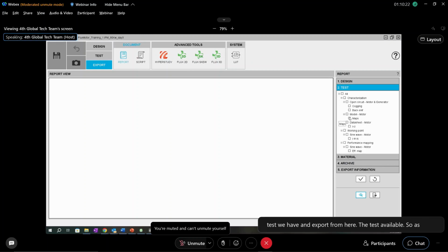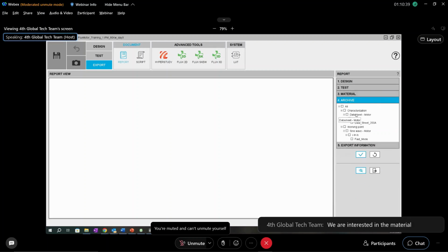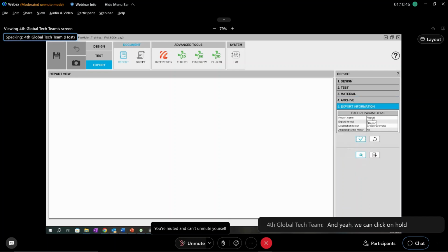So as you can see, we have a lot of tests available. We want to, for example, export the results of the open circuit tests and also the working points in wave. We are interested in the material, and we can click on all to export all the tests that we did.